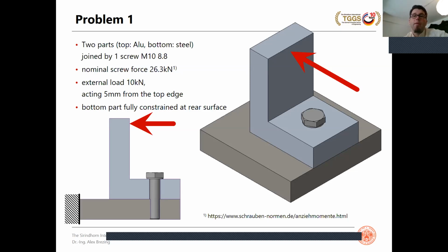Even worse, of course, in dynamic cases, the screw will loosen, but that is nothing that we are going to look at now. So basically, the main reason why you would want to run the simulation first is to make sure that the aluminium part will have stress levels that seem to be feasible, right? So the next question is, what do you really expect? Where would you guess the critical area is? What is the area with high stress levels that might need to be optimized by design?